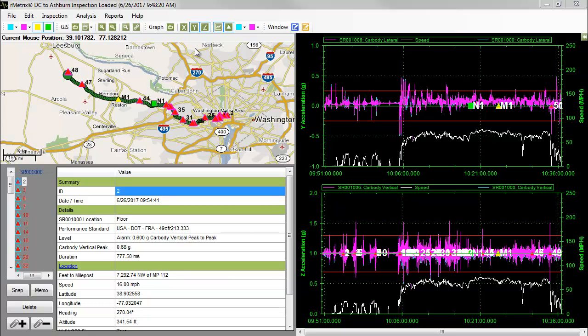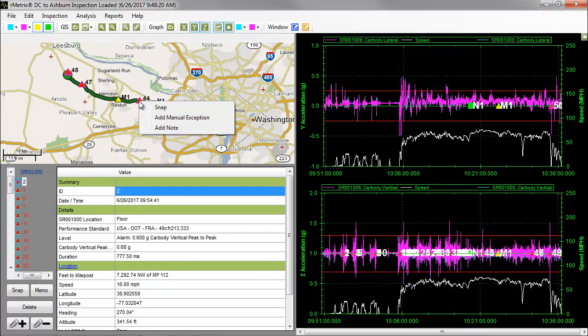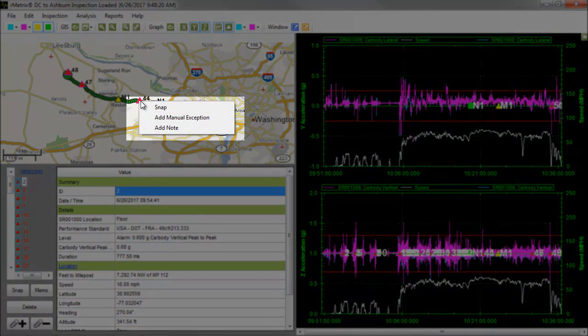During a live inspection, if the GPS has a fix, the information bar will be green and display time, latitude, longitude, fix type, and speed. When the GPS does not have a fix or is disconnected, the information bar will be red and will state no fix or GPS disconnected. The software will attempt to reconnect to the GPS on a periodic basis after the GPS receiver has been disconnected from your computer.